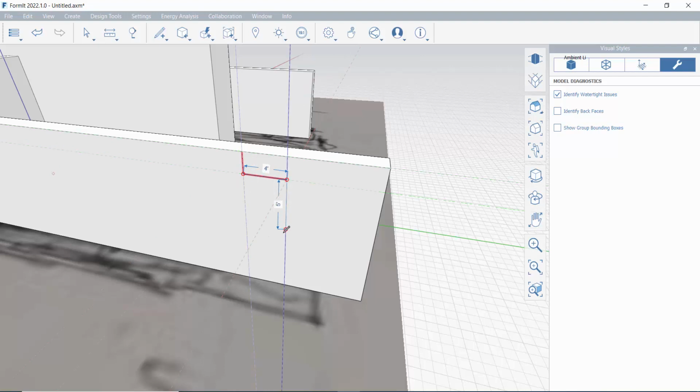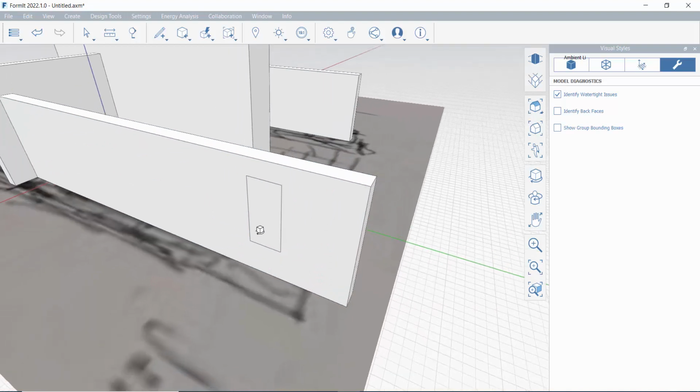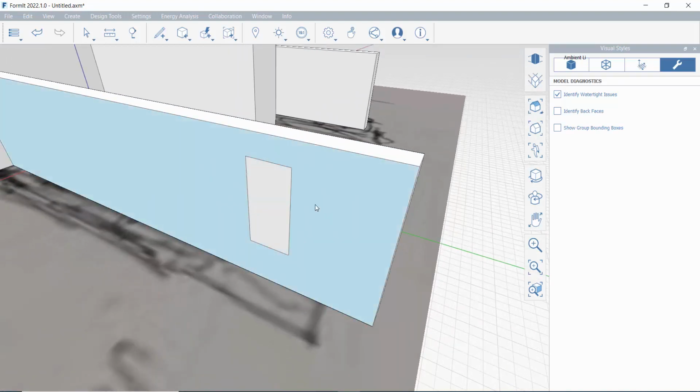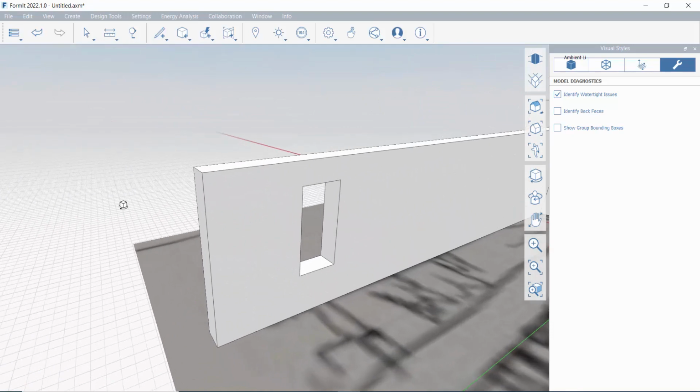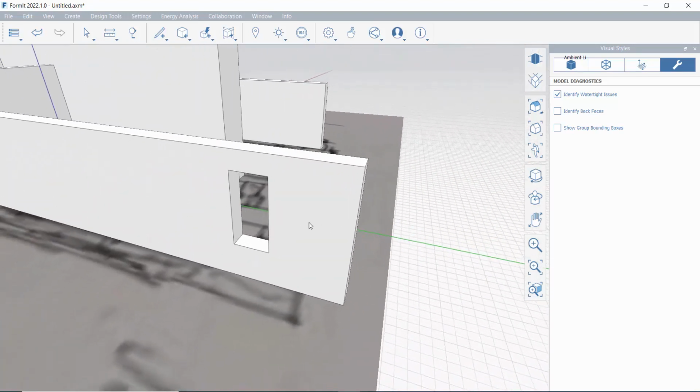4 feet over, 8 feet tall, and then I want to close that box off. Got that red line, I can delete it. I only drew that in as a guide because I didn't want it to be arbitrary from the top down, because dimensions matter. Okay, so now this object is divided up into 2 surfaces. I can now take that surface, push pull, and go right to the other edge. And it's cut a hole.